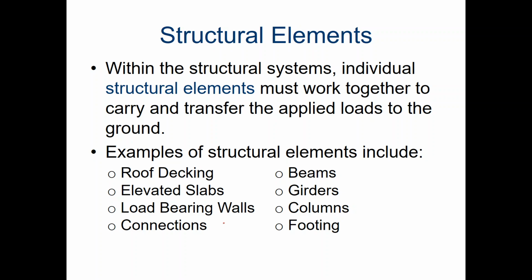All right, so let's see. All of these structural elements that we're going to talk about as we have things chasing through, starting with the roof deck and the slabs, which are the floors on the different levels, then to the load-bearing walls, through the connections, beams and girders, to the columns and to the footing. These are in order of how this is actually going to be chased through, and these are the terms that we're going to be using as we discuss the loads being chased through the building all the way down to the footing and then into the ground from there.